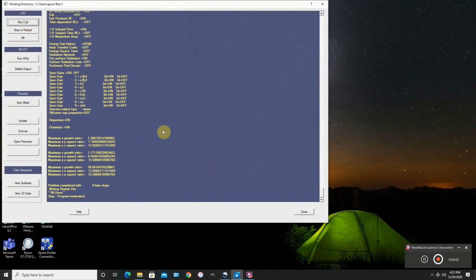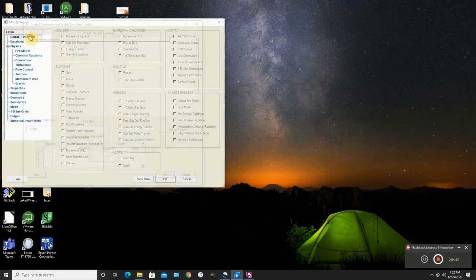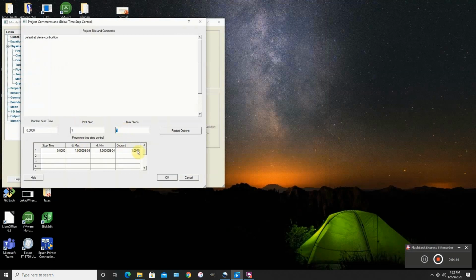Looks like it ran just fine. So let's go and, might as well just run it for a long time. Let's go in and modify the time steps. We'll make this 20. Oh, let's make it 10,000.